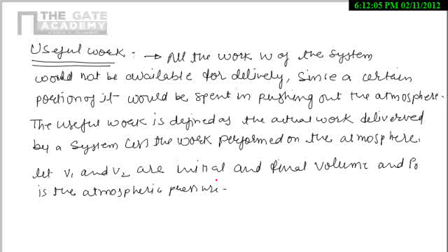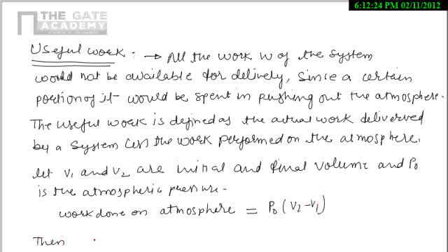So the work done on the atmosphere will be P naught into (V2 minus V1). Then the useful work, denoted by WU, will be W actual minus P naught (V2 minus V1).